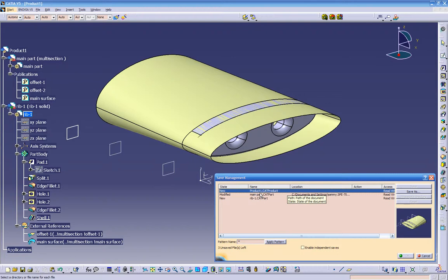Every time we save those files, we always have to make sure they are under the same folder. Because if you're trying to open the CAT product alone and it doesn't know where those files are, you won't be able to open it, and it's asking, hey, where's the location? So I always make sure to have a folder for each assembly individually. Like you saw me earlier, I'm going to save all this in the same folder.